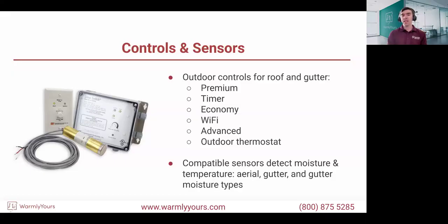Yeah, having both sensors gives you the best snow detection, because you don't need simultaneous input from both sensors. If one of the sensors is getting that snow or ice detection, then the system gets triggered. So you may have free-falling snow, where both sensors are most likely going to get triggered about the same time and the system is going to kick on. That's great.